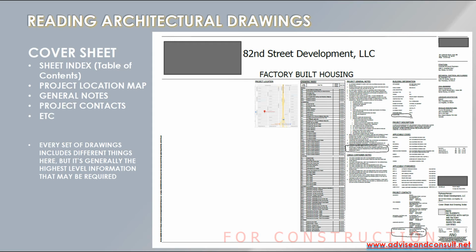So here is the drawing index that we talked about. Most of the information on the cover sheet is specifics of which building codes you're complying with, the names and phone numbers of the various constituents of the project, the architect, the various consultants. Project location is something that's always required by building departments around the country. That's consistent, so you have to identify where the project is.